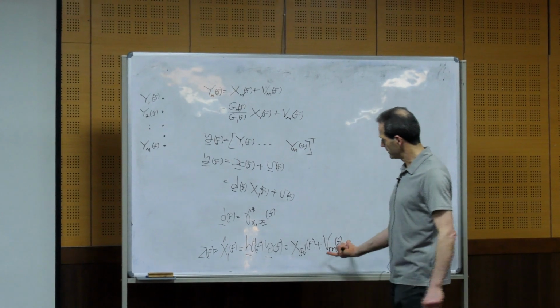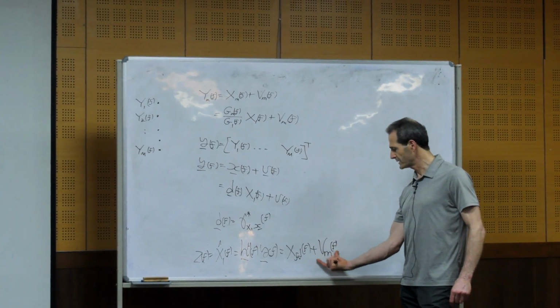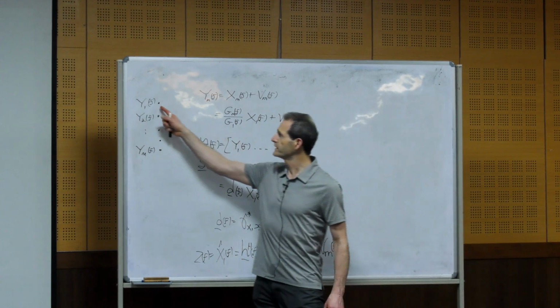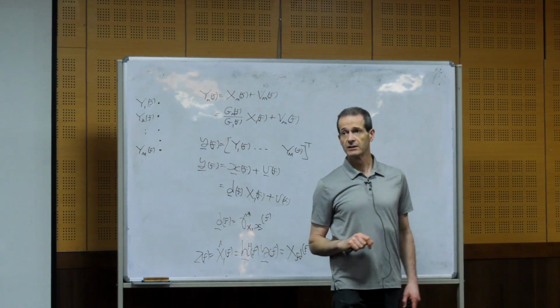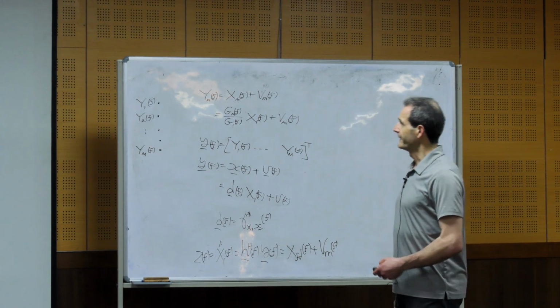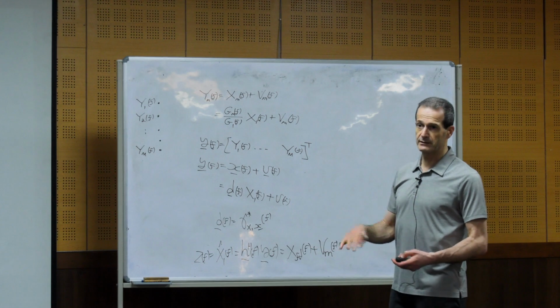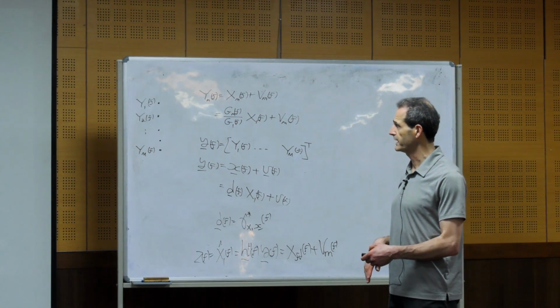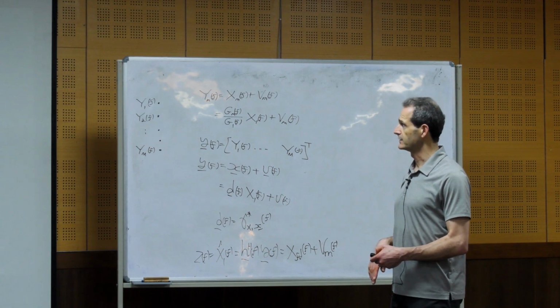So we can check the variance of the residual noise. What is the variance of the residual noise compared to the variance of the noise in the reference sensor? So this is the noise reduction factor. And we can define narrowband and broadband for each performance measure. And then we can also define the desired signal reduction factor.